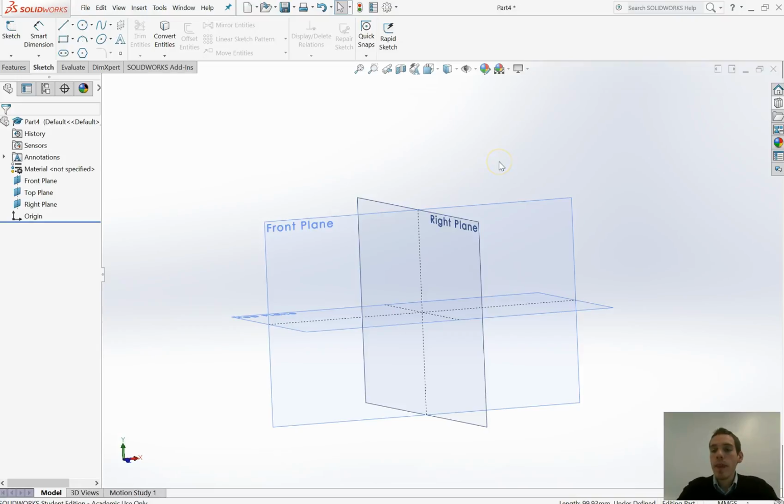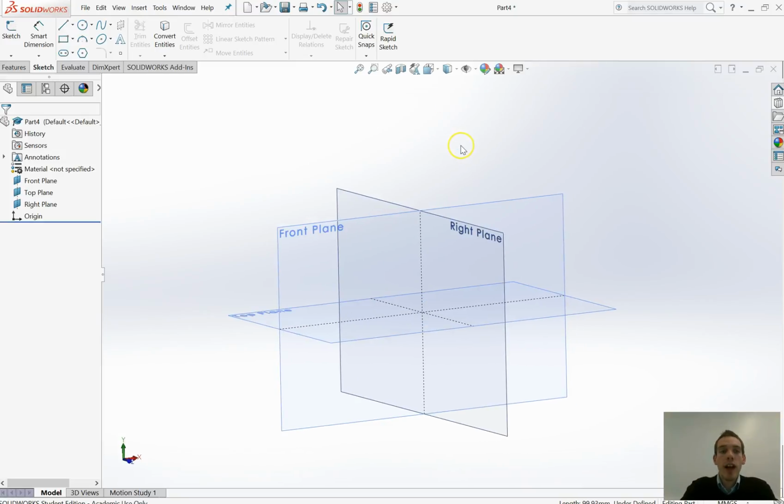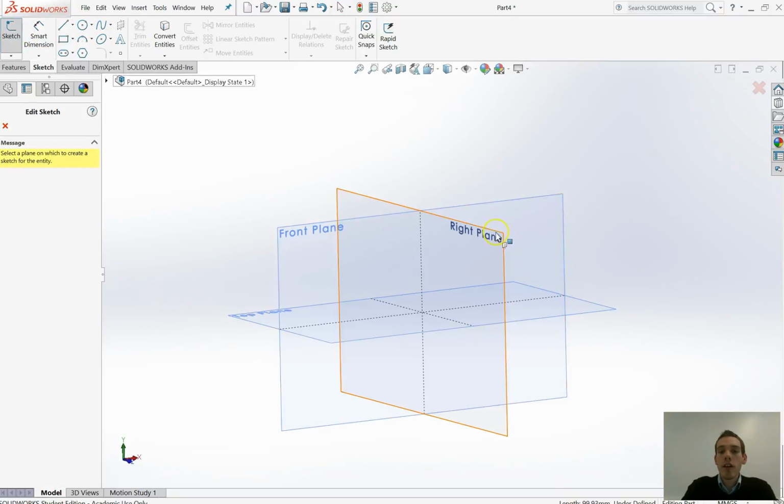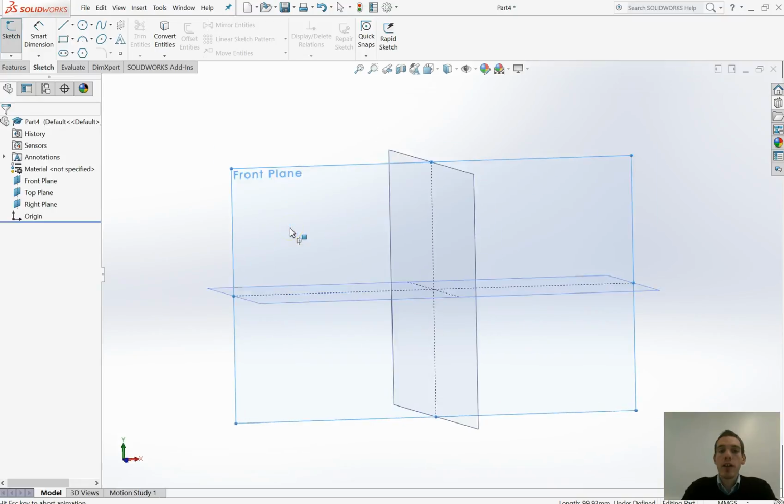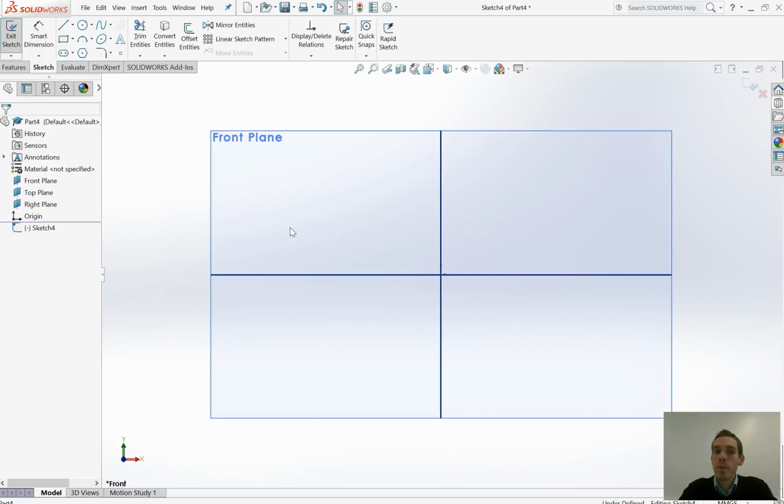What's it useful for? Well, traditionally we might use it for, I don't know, if I'm designing a candlestick, a chess piece, a cup, or anything that we want to have a constant cross section that is being rotated around 360 degrees. Okay, so the first thing we need, open up a part, and we need to have a sketch. So go and click on sketch and click on the plane that we want to sketch on. I'm going to click on that front plane to start with.